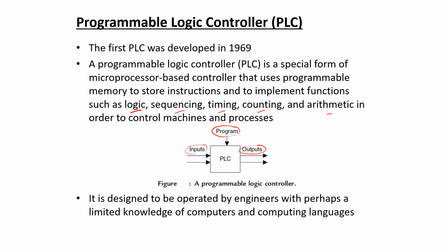In order to store the program that is written by the user, or in order to store the data, you need some memory units as well, in the form of RAM or ROM. In case of a microprocessor, the RAM or ROM memory units are not an integral part of the microprocessor. They have to be externally connected with the microprocessor.